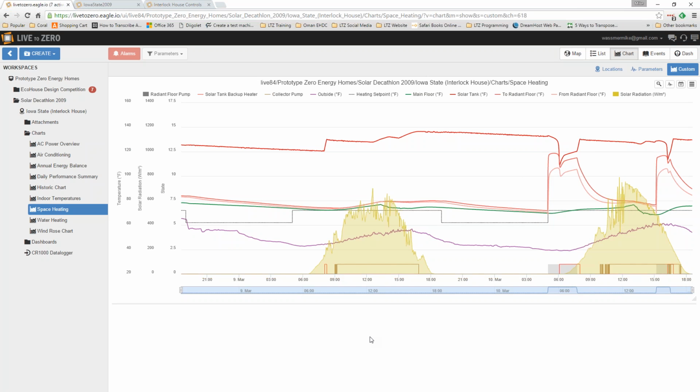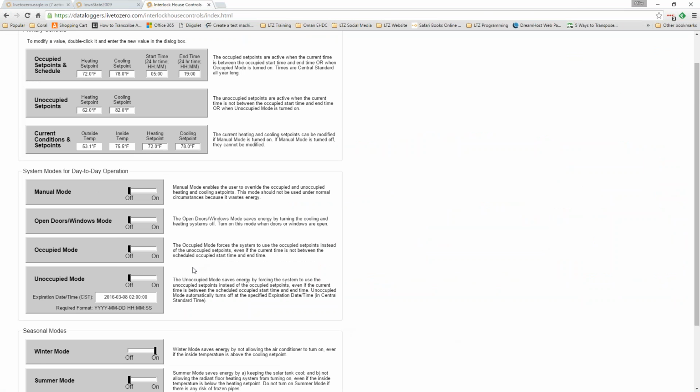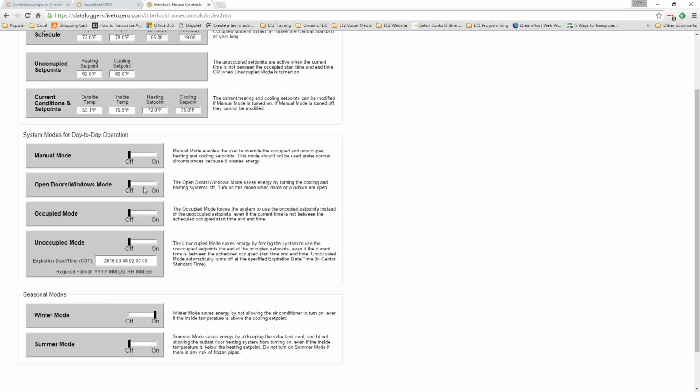Just one more question. Can we have the heating turned off during the weekend when it's vacant, so I can calibrate a baseline model without heating? Yes, I can. You just have to tell me. The easiest way to do it is to say to the system that the windows and doors are open, and that disables the heat.